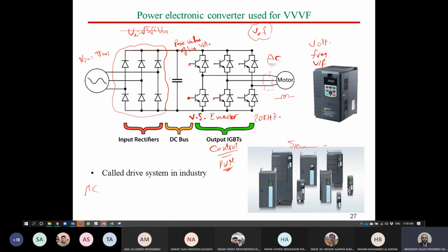However, you can equip it with another processor that the PLC can control as well. But the code of pulse width modulation will not be written on the processor of the PLC itself. It needs an external device, okay? For that, a microcontroller is preferred.